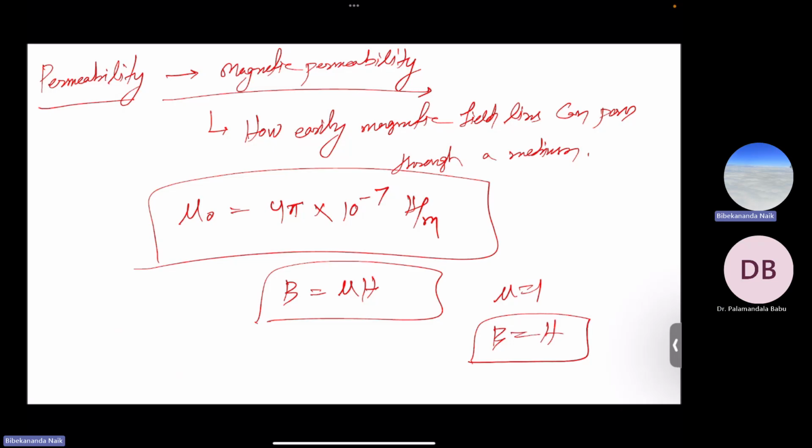And if you talk about the vibrating sample magnetometer that was also explained, basically this vibrating sample magnetometer works on the principle of Faraday's law of electromagnetic induction. It is basically used to study the magnetic properties of materials. We know depending upon the magnetic properties, materials are classified into three types: diamagnetic, paramagnetic, and ferromagnetic. These types of material properties can be studied through this vibrating sample magnetometer.